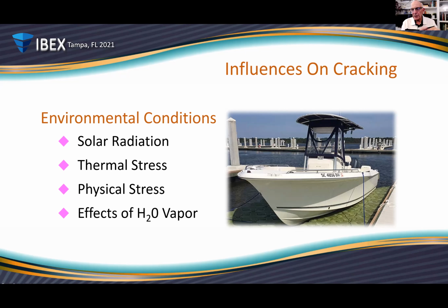Back many moons ago, in my Viking Yacht Company days, before Viking built the new plant that they operate in now, the hulls would go up the assembly line and the decks went outside. And in the winter, when a 40-foot deck was brought in and set on a hull, it would be an inch shorter than the hull if it was cold out. And they would basically have to let the deck sit there overnight, and then the next morning the deck would fit.